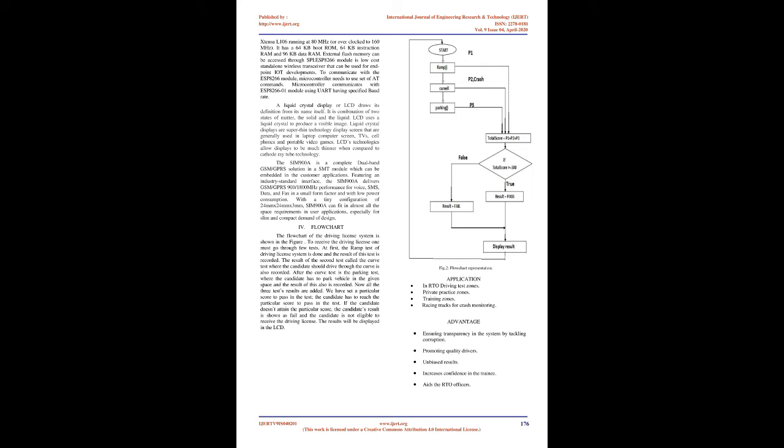An infrared sensor is an electronic device that emits infrared radiation in order to sense some aspects of the surroundings. An IR sensor can measure the heat of an object as well as detect motion. These types of sensors measure only infrared radiation, rather than emitting it. That is called a passive IR sensor. Usually, in the infrared spectrum, all objects radiate some form of thermal radiation.